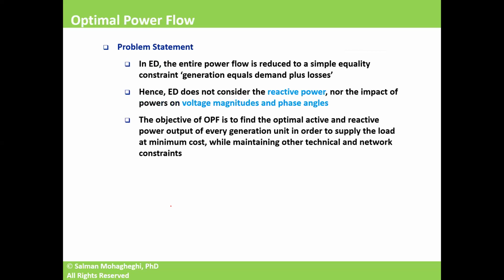After we have run unit commitment a day in advance and economic dispatch, let's say every 30 minutes to an hour during the dispatch day, we would have to run optimal power flow between the solutions for economic dispatch. Here's the thing. In economic dispatch, as you saw in the previous slide, power flow is not explicitly modeled typically. So in most situations, we look into a very simple constraint of generation equals demand.